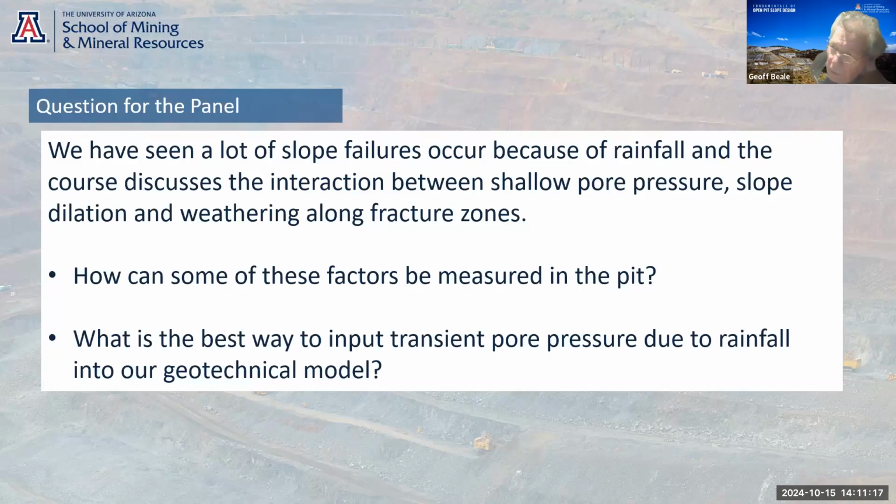And you can vary the RU, and if you've got a good kinematic analysis, you can vary the RU to the point where you can see where the instabilities occur, and then those are your focus areas in the pit. So keep increasing the RU, see where your instabilities are. Those become your focus areas, and those are also the areas to focus your surface water control. So that's a very good question, very topical question. Lots of instabilities because of this. So let somebody else have a go at that too.